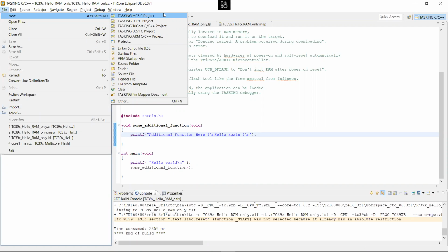That's a separate compiler because that's a separate core with a completely different instruction set that works basically independent of the Tricore core and does real-time arbitrary data processing of input data and output data and so forth. It's a very powerful core that allows you to freely program input and output real-time processes within the general purpose timer module. So something that goes way beyond just having a little PWM or so. But we've got a compiler for that in this tool chain too. But right now we are going to stick with the Tricore project.